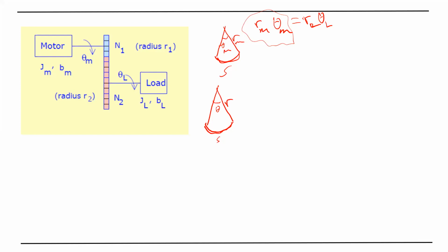Yes, Doctor, this is from real life. The backlash is the small distance between the teeth before they start engaging. But here we are assuming they engage immediately. There is no backlash. There is another course in nonlinear control systems that studies the effect of nonlinearity. What I'm trying to warn you is that there is an approximation here. In real life, everything is nonlinear, but we are approximating.